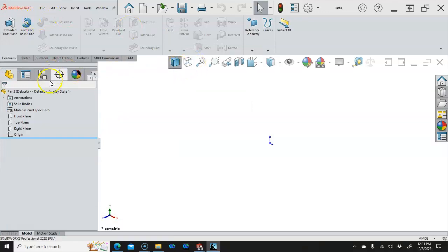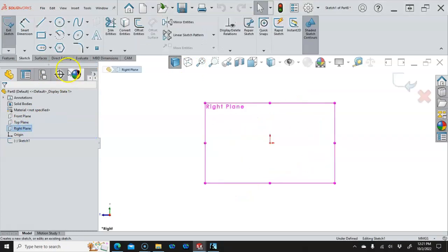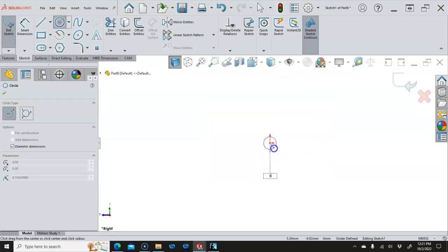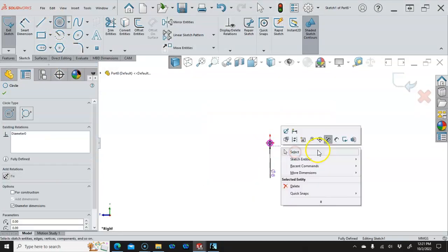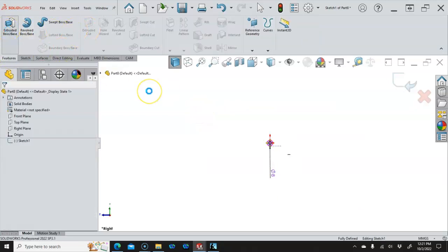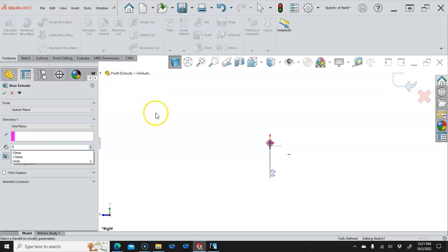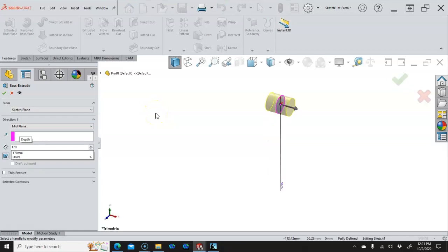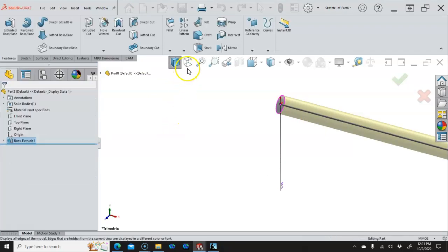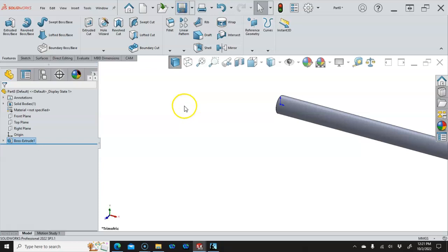for the shaft, and this one I'll put on the right, 8 millimeters. Let's go ahead into the extrude, 170. Don't know that I want that one on the midplane, so we'll switch it back to a blind condition and save that.